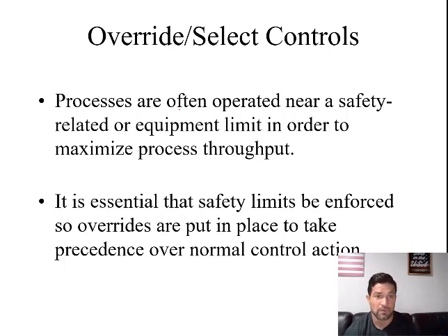Again, this is important because processes often operate near a safety-related or equipment limit, and we want to prevent the system from going over those limits. The safety systems must be enforced so that the overrides take precedence over the normal control action.